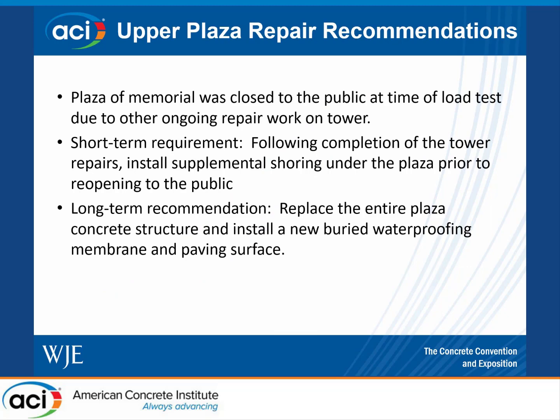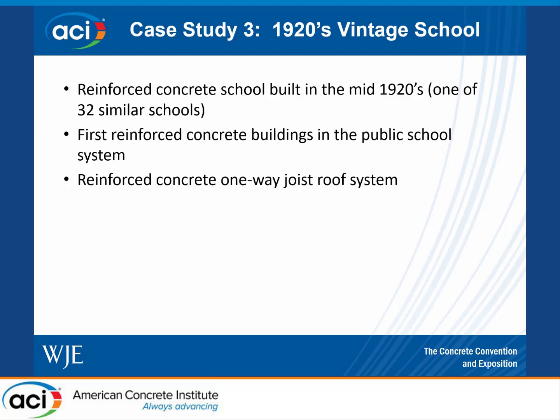So our recommendations at the time, well, when we were doing the load test, the plaza was closed to the public because they were doing other projects higher up on the actual memorial itself. The short-term requirement was, following the completion of that work, we recommended that they shore the plaza area prior to reopening to the public. And then the long-term recommendation was to repair or replace the plaza level structure and install a new buried waterproofing membrane and pavement surface above.